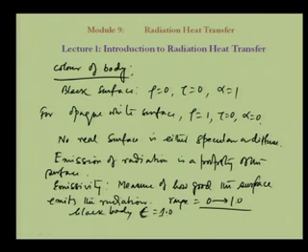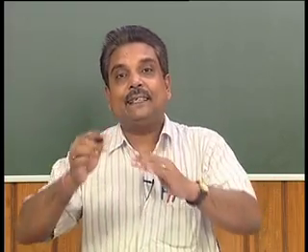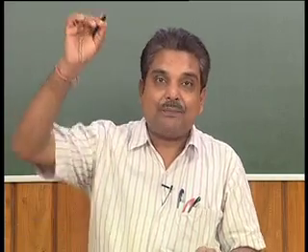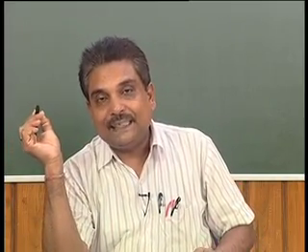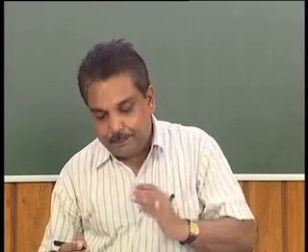And it is expected that for the black body, basically the emissivity and emissive power have a datum, and datum means the upper ceiling of the emissive power is given by the black body. So, it is the black body that is supposed to emit maximum radiation at a particular temperature, and therefore the emissivity or emission power of the black body is the highest, and it is equal to 1.